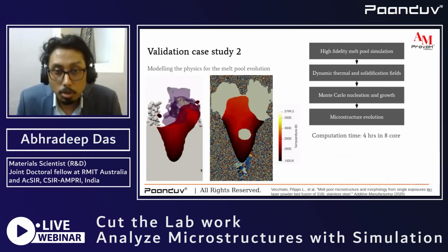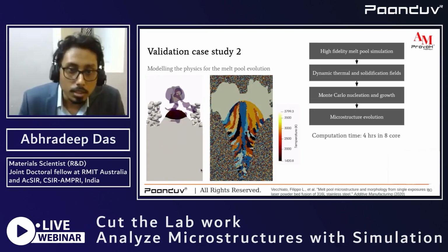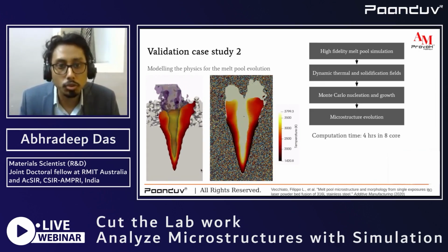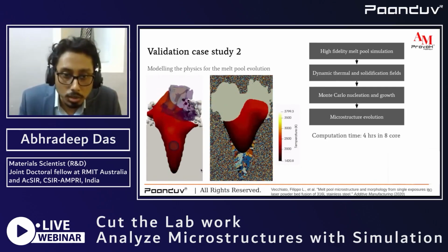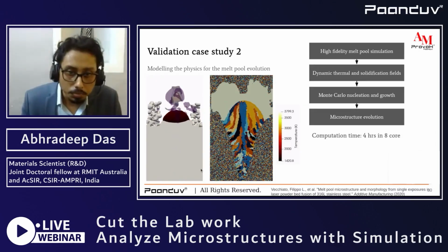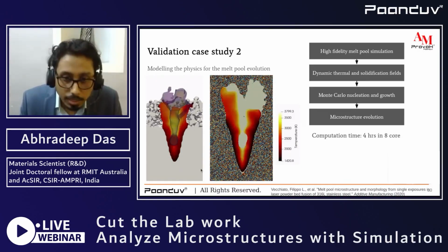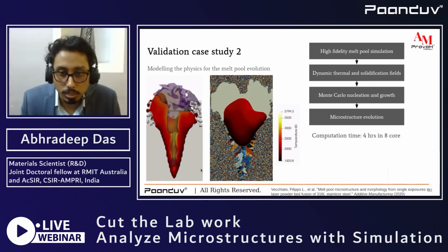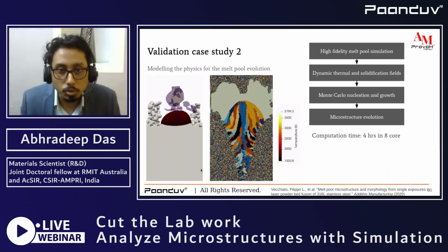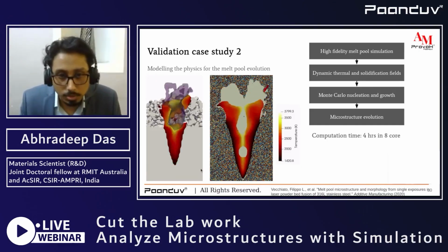Herein I will be discussing the mechanism. You can clearly see with the images here how these multi-phase simulations are useful to decipher the actual microstructure evolution. You can see how the microstructure analysis gives us detailed insight into the formation of the microstructure, in which we can see how the vapor entrapped gas pores can be modeled using the four-phase multi-phase system that we generally use.